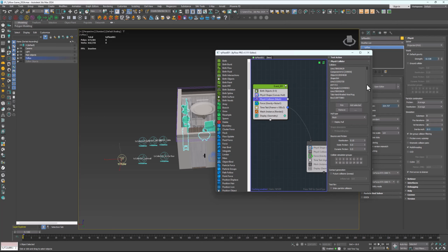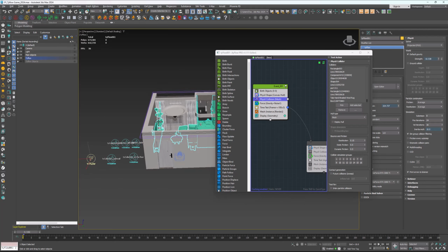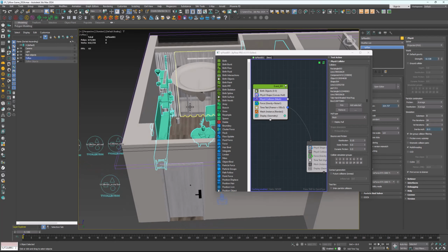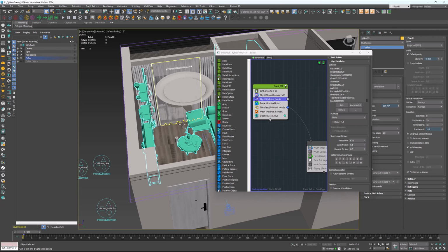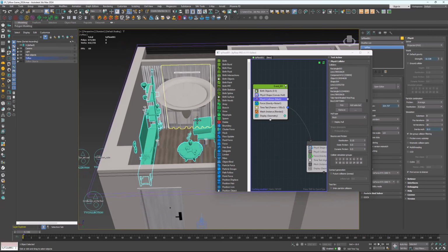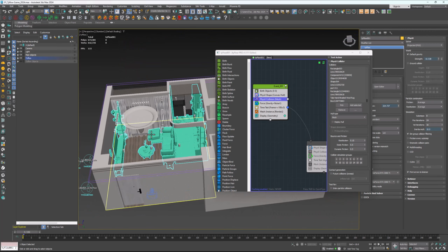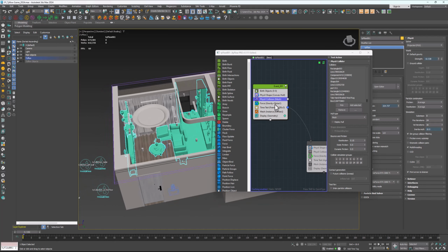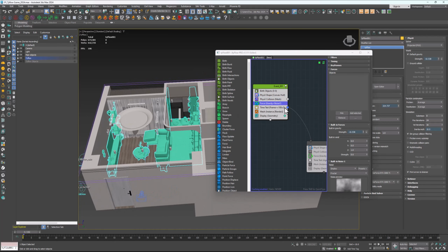I added lots of objects, for example the floor, walls, ceilings, curtains, and all other objects that I want to have a collision, and then add a force gravity, and I just click on it and put in the real world value. This is the real world value, and it may be a different value with your units.